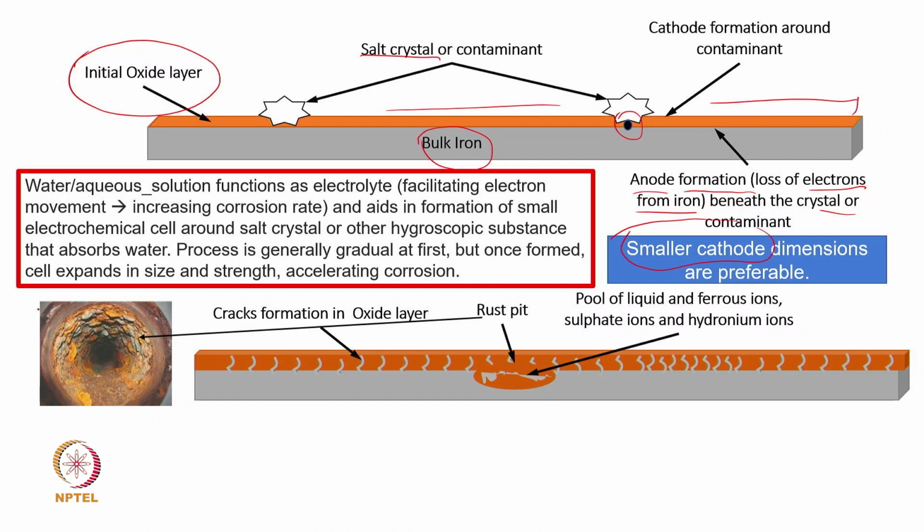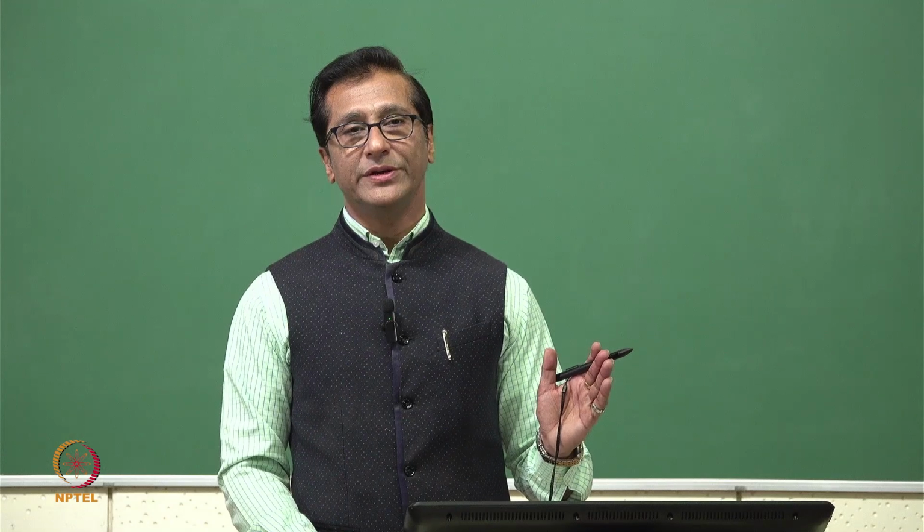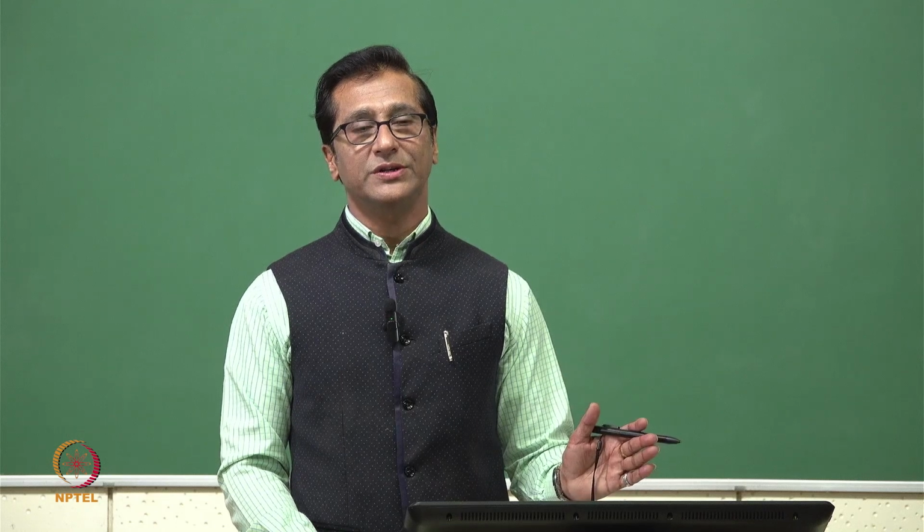Now here it has been shown very clearly how the cracks are getting generated, and then iron oxide forms, and maybe water gets ingress in these kinds of patches, and it gets worn out very fast. Now if there is any cylinder which is moving in and out, naturally the wear rate will be very high, and there will be continuous exposure of the virgin surface getting oxidized and getting removed also. The clearance will be much larger. So this is what we need to avoid.